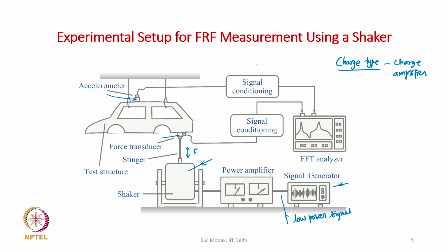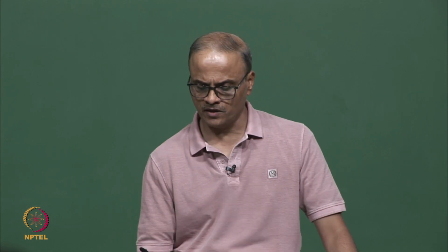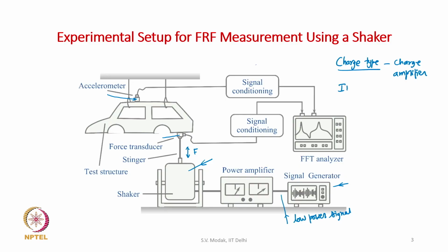The second possibility is that these transducers are of IEPE or ICP type, as we discussed in one of the previous lectures, and the FFT analyzer also has input ends which are compatible with such types of transducers.